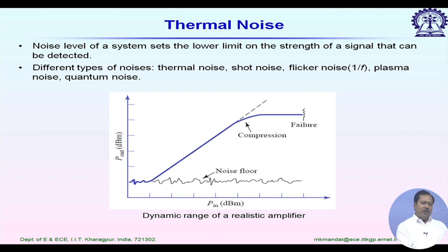Now let's say we have a millimeter wave component. It can be an amplifier also. For any amplifier, the gain will be specified. You can consider not just a millimeter wave amplifier, it can be a very basic common emitter amplifier. If you remember from our UG first year class, we tested the signal handling capacity of a CE amplifier. The amplification factor is given, then we change the input power level and measure the corresponding output power.